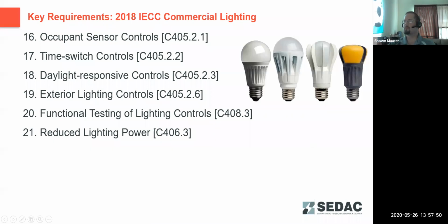And now, before we move into the lighting section with Ryan, we've got one more poll about mechanical demand control ventilation requirements: which is not an exception to the requirement for demand control ventilation? Systems having full energy recovery, multi-zone systems that do not have a central control panel. You can go through the rest of the options there, and we'll try to touch on some of the questions that have come in through the mechanical portion.